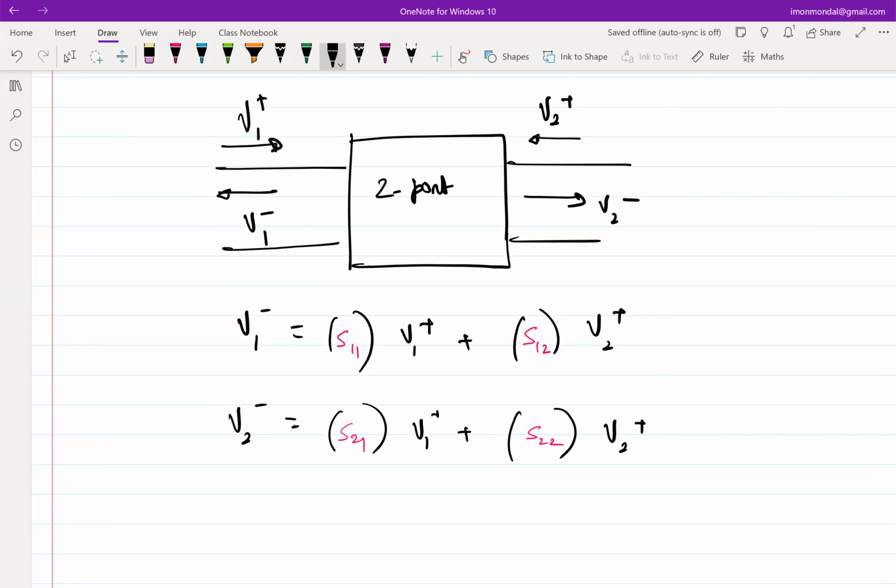Now, how do we find out this S11 experimentally? Firstly, I'm recapping, what is the necessity of going into this set of definitions? It is important because ultimately the goal of going to a different parameter was to ensure there is no reflection, right? Which essentially means that I have to find out a condition in which your V1 minus and V2 minus can go to 0. If there is no reflection, there's no problem, right? So under what condition then, let's assume V1 minus can go to 0.